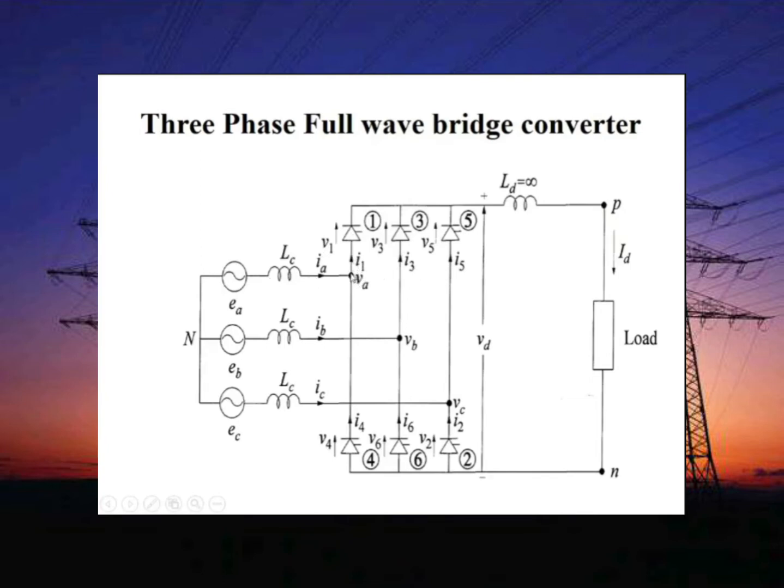Therefore, the phase-to-neutral voltage of phase A becomes more positive than the voltage of the other two phases, 3 and 5. The valve starts conducting, meaning this phase becomes more positive compared to the B phase and C phase. At that time, valve 1 starts conducting. The common potential of the cathodes of the three valves is then equal to that of the anode of valve 1. Since the cathodes of valves 3 and 5 are at a higher potential than their anodes, these valves do not conduct. In the lower row, this terminal is the anode of the valve.